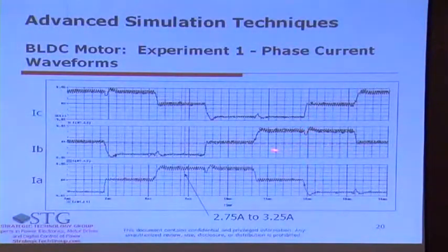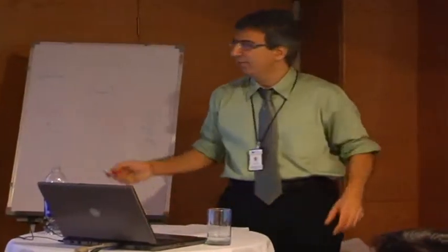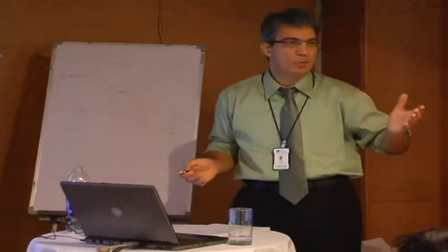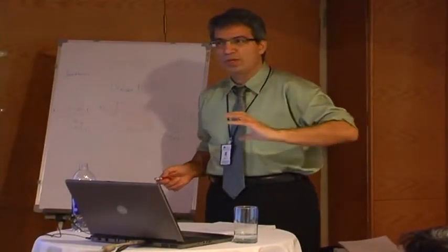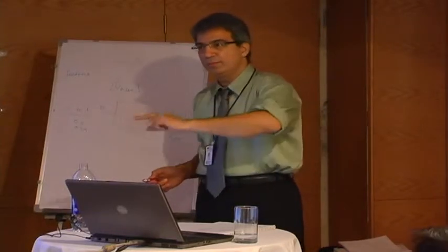And this dip is related to the inductance of the motor and the reverse recovery of the diodes. As the inductance of the motor increases, this dip will become deeper. And for some motors you cannot use the BLDC algorithm. When the inductance becomes too large, the BLDC algorithm will not work for those motors, at least in this type of scheme where you have a high side PWM, just because at that point of time you need better control over the current. You need all PWMs, which allows you better control over the current to control the motor.